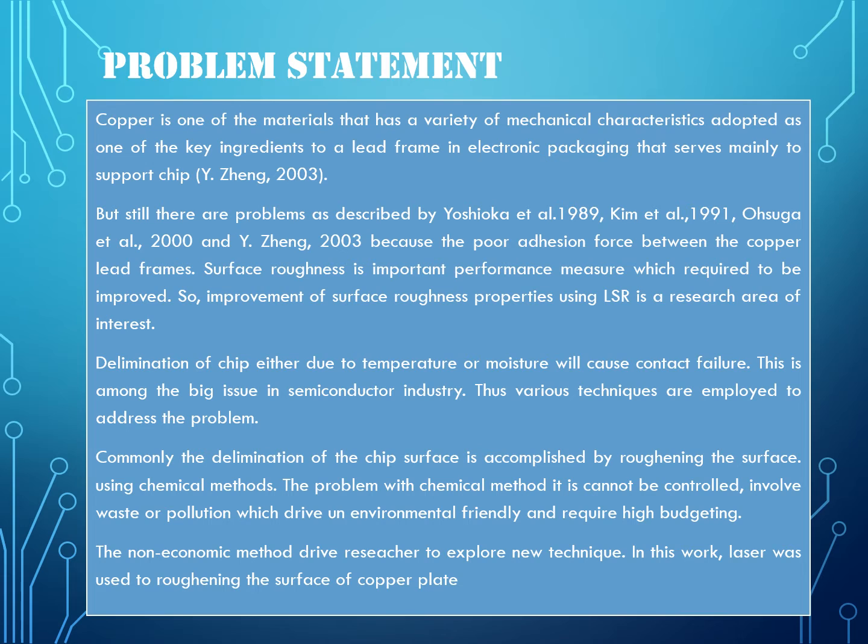Various techniques are employed to address the problem. Commonly, the surface roughening is done using chemical methods. The problem with chemical methods is that they cannot be controlled, involve waste or pollution which is not environmentally friendly, and require high budgeting. So the need for an economic method drives research to explore a new technique. In this work, a laser was used to roughen the surface of a copper plate.